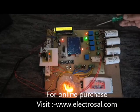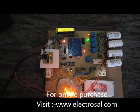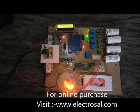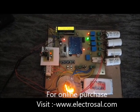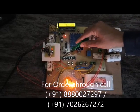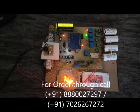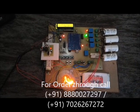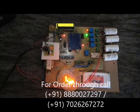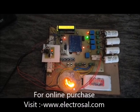Now as you can see, the system is in lagging mode and the capacitor fluctuation is eliminated. Even though the Arduino processes only the inductive load waveform, the power factor is improved at the back end and we can clearly observe real power, reactive power and apparent power values. Additionally, the system also supports manual mode. Using the switches, we can manually add or remove capacitors and observe how power values change in real time. This demonstrates both automatic and manual power factor correction in our project.